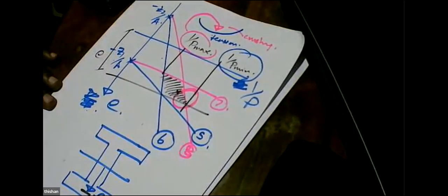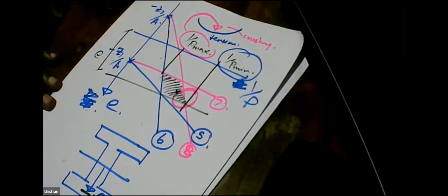We should select the pre-stressing force as low as possible, because then when the pre-stressing force is low, when we apply the full loads, the beam can crack, and when the beam cracks at the bottom, the yielding of steel will occur, and we get plenty of warning that something is not right with the beam. So we have enough time to evacuate.